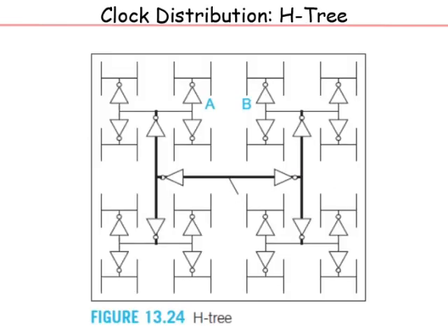Now, how do you distribute these clocks such that you have a minimum skew? Imagine that you have a clock source out here at the center of the chip. One approach is some kind of symmetry. We try to make things symmetric. In that spirit, this kind of architecture evolved. This is called the H tree, because you see there are all H's.